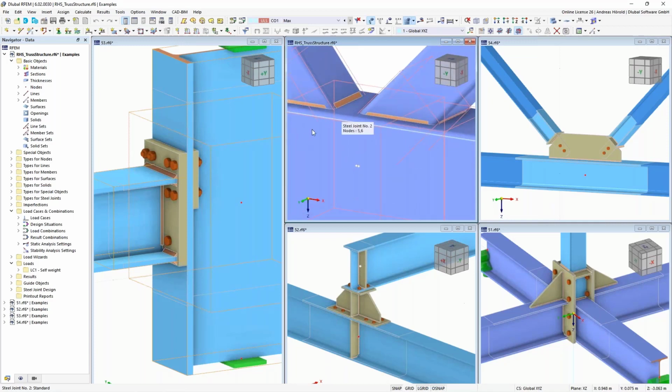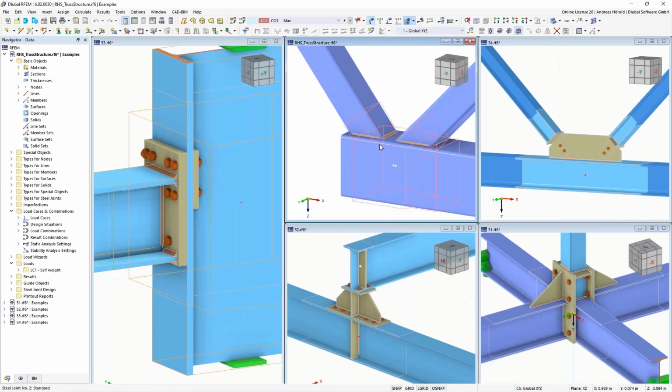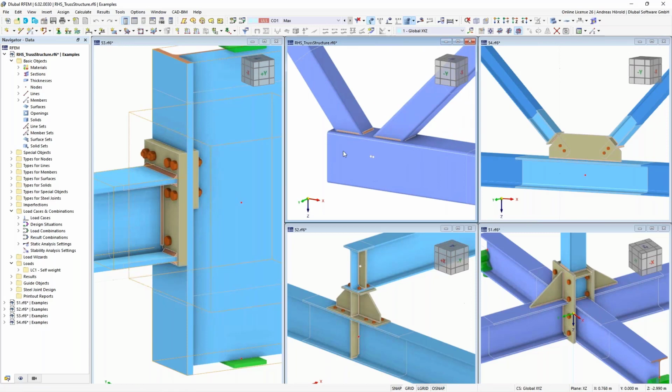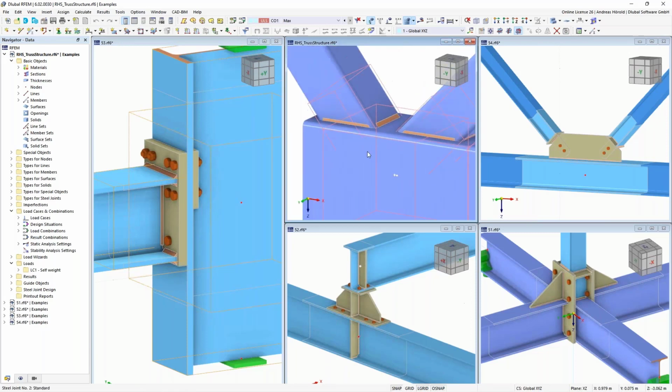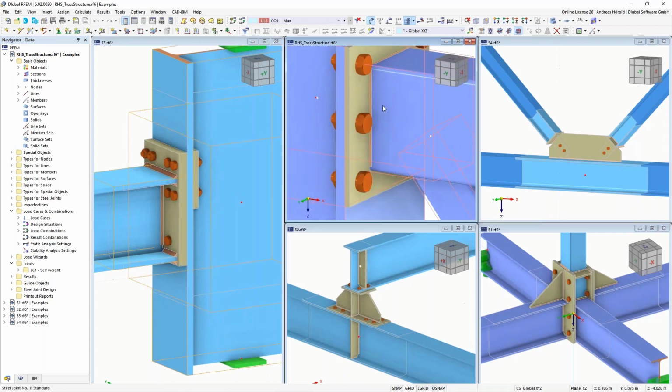You can see where the weld on the fillet is missing. We are working on it. At the moment you are on the safe side. Only the straight components are connected. We are working also on the implementation of the round hollow section, and when we release it, I think also the welds on the fillets here are ready. Also such a connection.